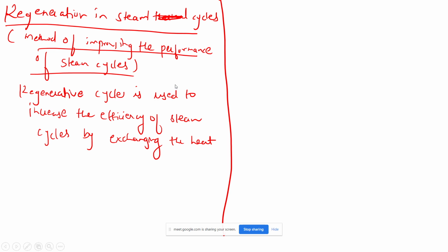No, because in the gas turbine, we use the steam after the exit of the turbine. But in the case of a steam turbine, if we use the steam at the exit of the turbine, it is generally in the wet region, so it will cause erosion of the turbine blades at the exit. So that steam we are not utilizing, and that steam will not have superior enough quality to heat the steam entering the boiler.